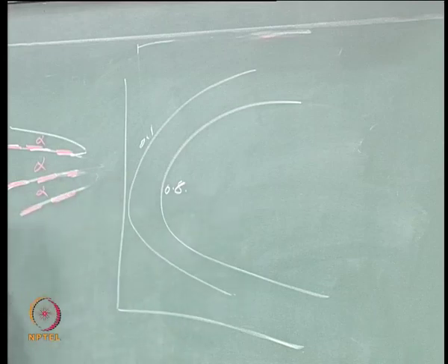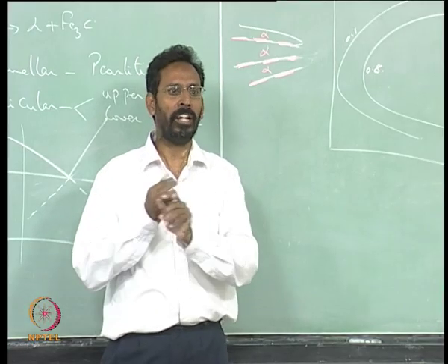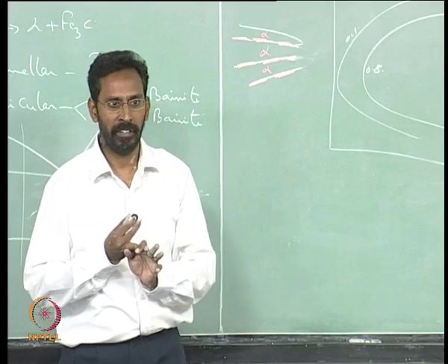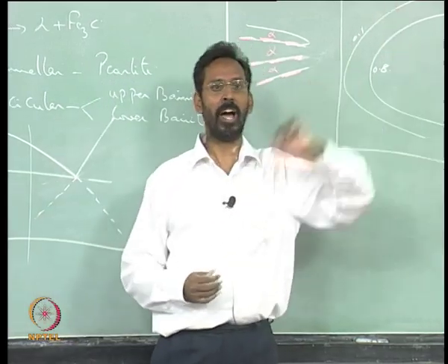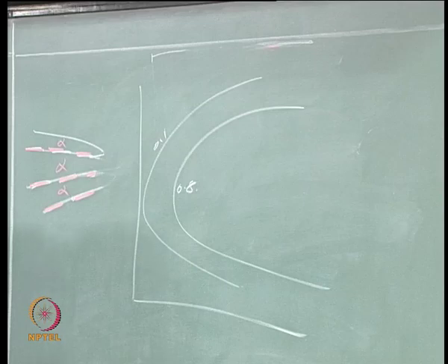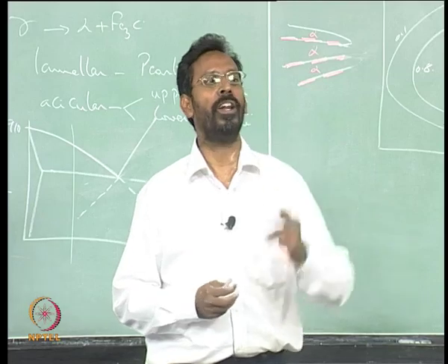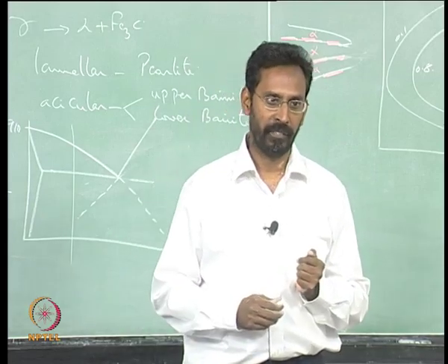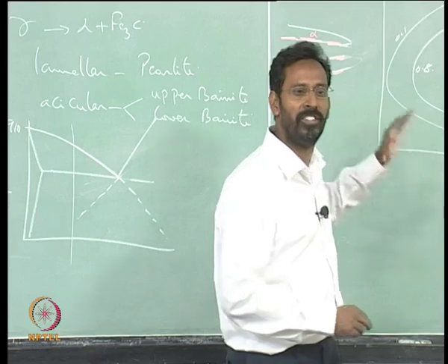If I decrease the carbon content, I am increasing the ferrite amount, and both are detrimental for hardenability. Whereas if I am increasing the carbon content beyond 0.8, that should actually increase the hardenability, but I am getting cementite, which should be detrimental for the hardenability. So you have two counteracting effects, and as a result you do not see significant shifts.